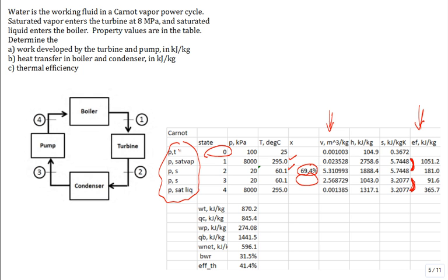For the dead state, temperature and pressure fix it. Oh, it's pressure and it's saturated vapor. Pressure and entropy, pressure and entropy, pressure, saturated liquid. Calculate the work of the turbine, the Q of the condenser, the work of the pump, the Q of the boiler, the net work, the back work ratio, and the thermal efficiency. This back work ratio is way too high. 31% of what comes out of the turbine has to be devoted back to this quote-unquote pump. This thermal efficiency agrees with 1 minus TL over TH, where you put in Kelvin. Okay? All right.